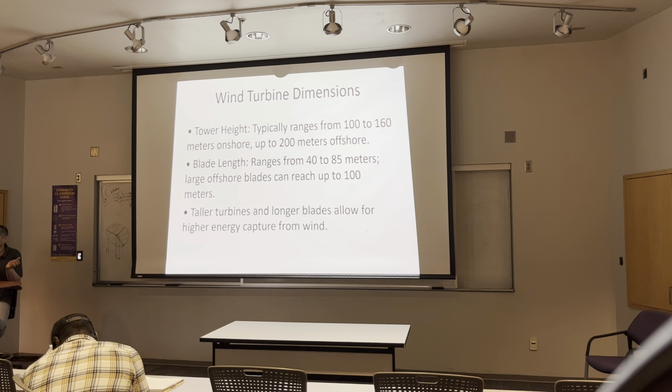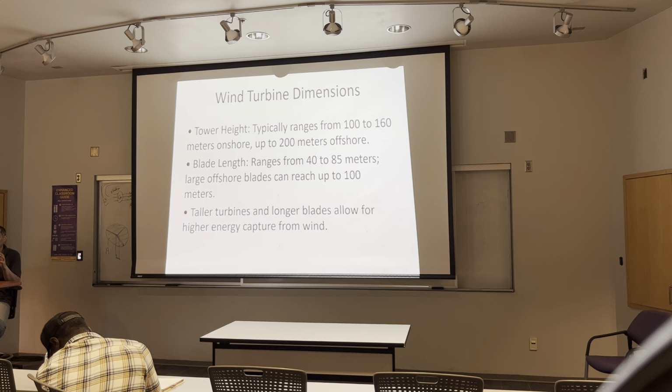For example, if we install outside this building, it's not going to work. It should be a wide area, and you should measure the air, wind pressure, wind speed, and direction for a long time, 1 year or 2 years, to test whether this area is suitable to install a wind turbine or not.